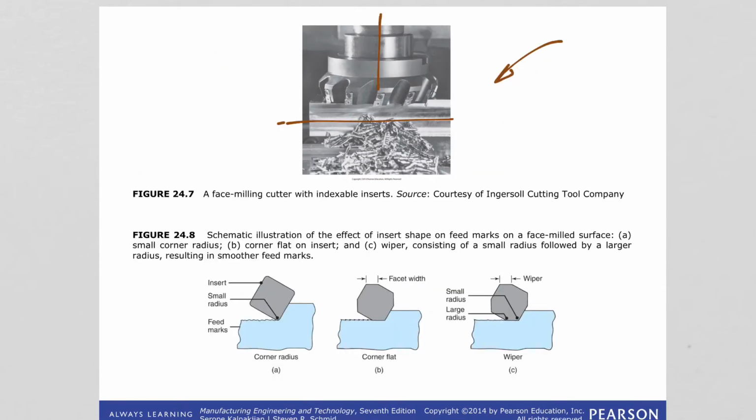So as you can see, milling is done using inserts. Here you can see them used to remove the material from the workpiece. It is because these inserts are replaceable, right? They are made of carbide, and that makes them durable at extremely high temperatures and during high-speed applications. This way we increase tool life.